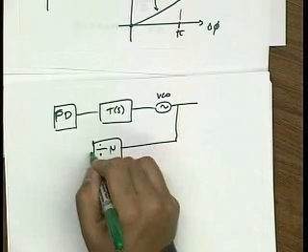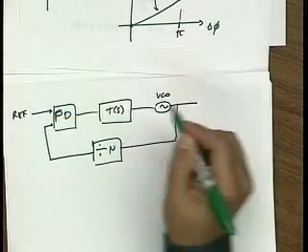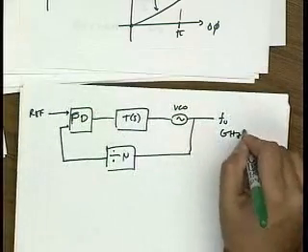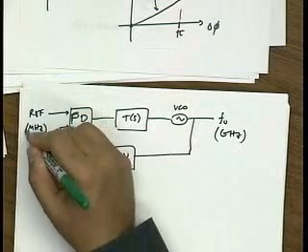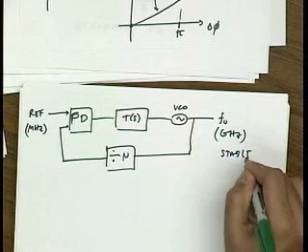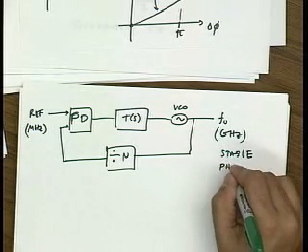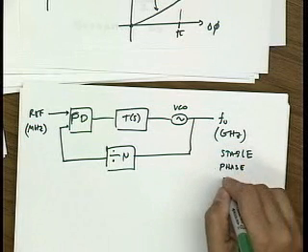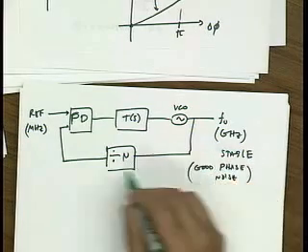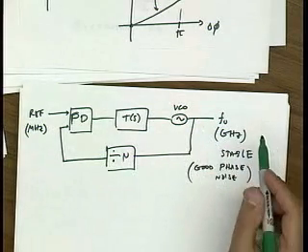So the beauty of this circuit is that, first of all, given a reference in megahertz, I now have a gigahertz signal that's very stable. We'll show you guys, probably next lecture, that it also has very good phase noise. Turns out that within the bandwidth of this PLL, I can clean up the phase noise of this guy.